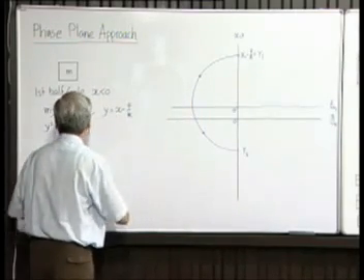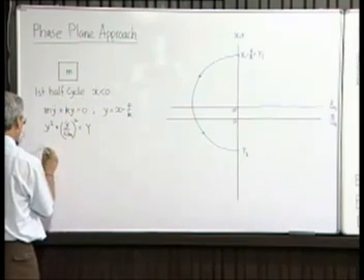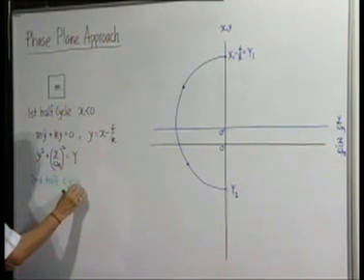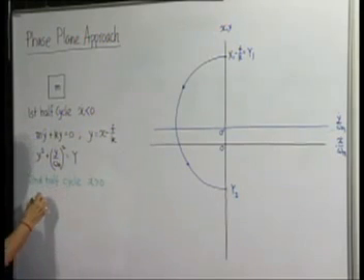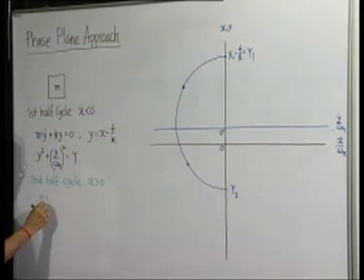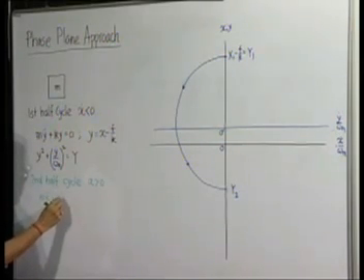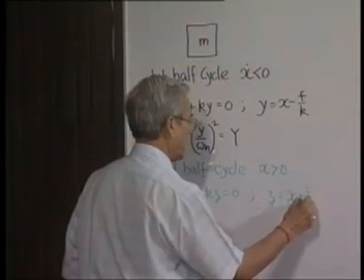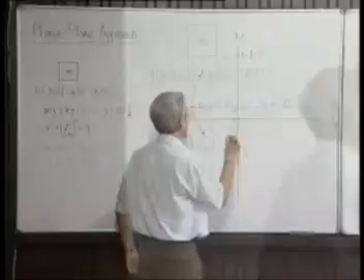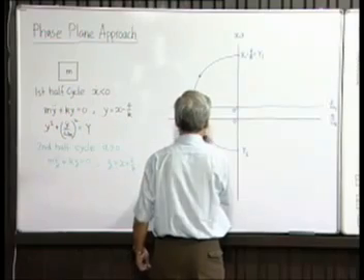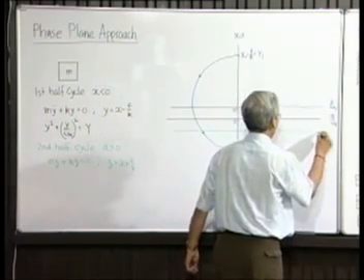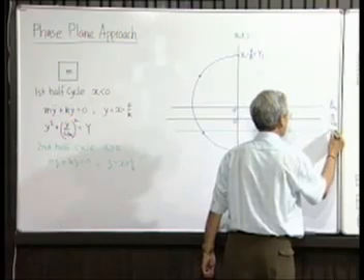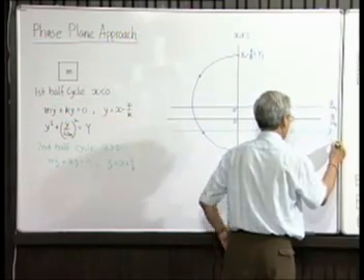Now, if you go to the second half cycle, x dot is more than 0, the equation is m z double dot plus kz equal to 0, where z is equal to x plus f by k. So therefore, now the new axis, the new origin will be here. This will be the z axis and this will be z dot by omega n.